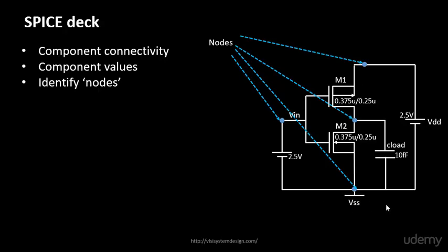Okay, let's pick up another component, for example this load capacitor. The load capacitor can be very well defined between this node and this node, because this is a node common to the VSS common node, and this particular node is present at one of the parallel plates of your output load capacitor. There is nothing else coming in.